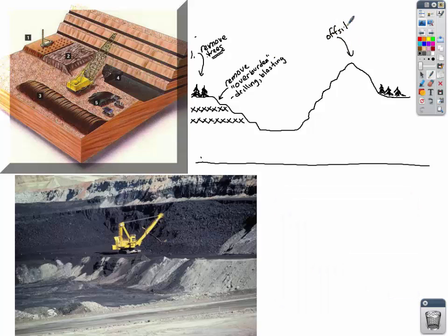So we're either going to put this off-site, or we're literally going to take the overburden and put it right behind us, and that ends up being done in a series of steps, which will create a man-made mountain behind you. Then later you can take that mountain and refill your hole. Now we've exposed the coal seam, the mineral itself, so we're going to excavate that mineral and load it onto trucks, sometimes trains, to transport for processing.